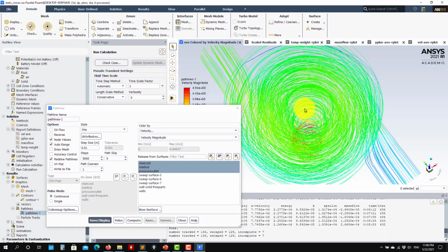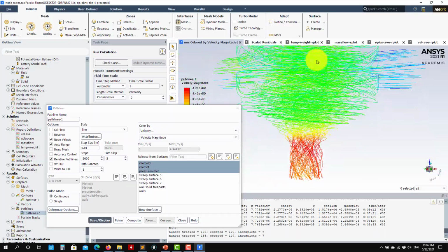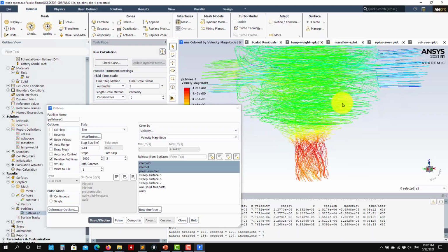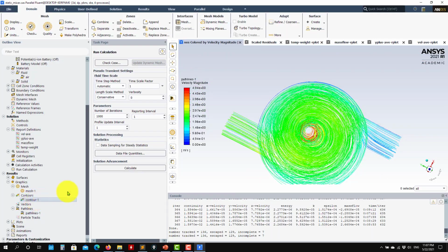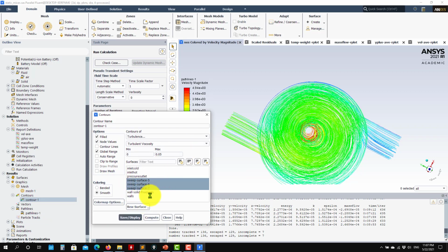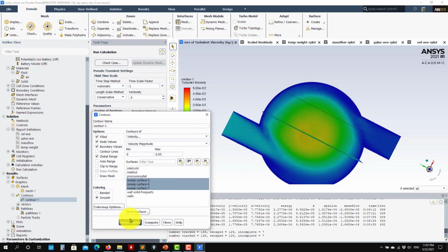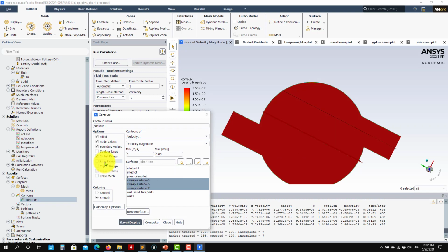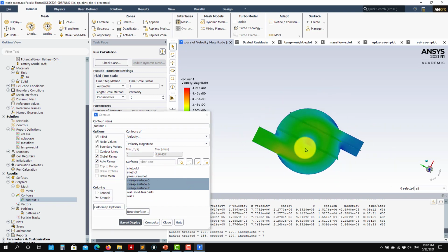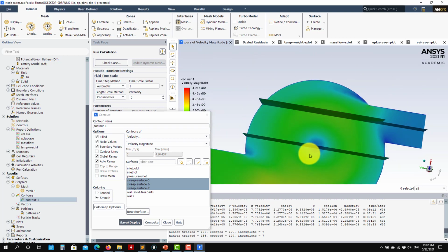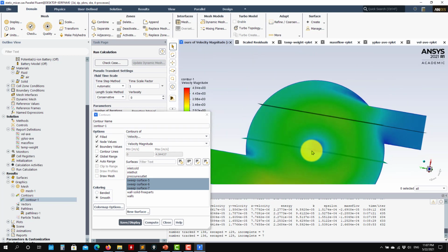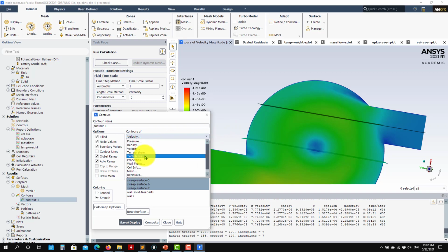So in the center we should have really low, and it's producing very, very high turbulence viscosity in the core. Okay, so let me go here, if I put velocity here, outer range. Okay, so see that in the center, that velocity is very low, and the theory tells us that if that is the case, why should we produce too much viscosity there? Okay, and this is the problem in this case.